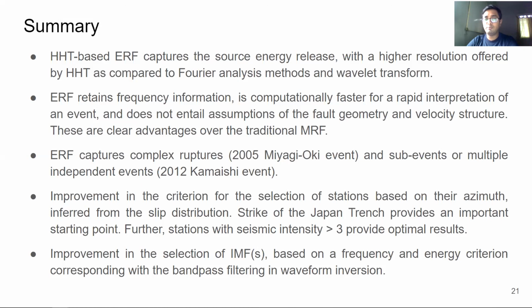We also make two improvements in the implementation of the proposed algorithm, to the selection of stations for strong motion analysis and the selection of IMFs. Stations within the azimuth inferred from the slip models, in addition to the orientation of the Japan trench, give optimal results for seismic intensity higher than 3. IMFs selected based on the frequency and energy criterion are used to generate an ERF that matches with the MRF.